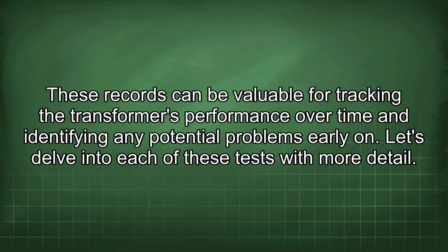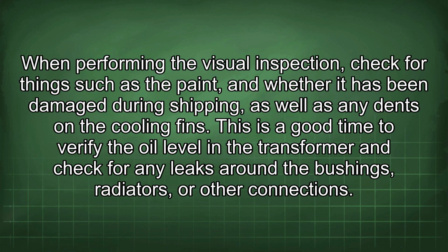Let's delve into each of these tests with more detail. When performing the visual inspection, check for things such as the paint and whether it has been damaged during shipping, as well as any dents on the cooling fins.